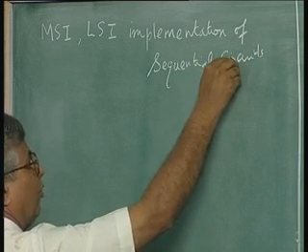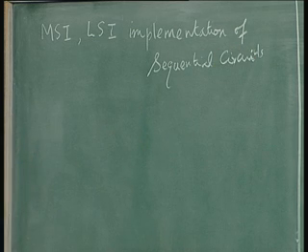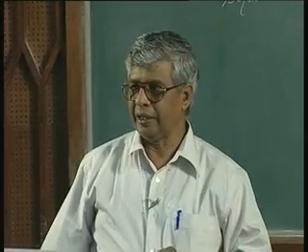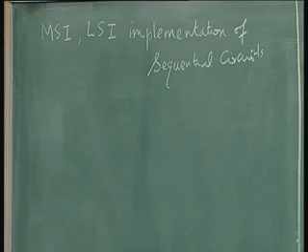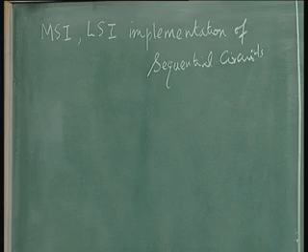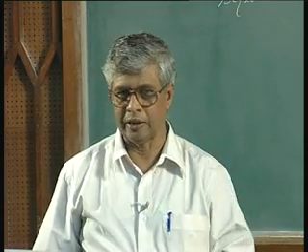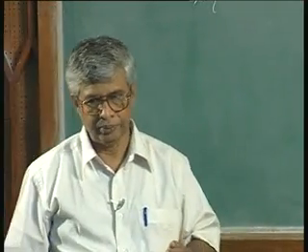I want to emphasize this point once more: when I say sequential circuit, it has a combinational and a sequential component. The combinational part will use all this MSI LSI we discussed. Of course, you will also see that we can do the sequential part too. For example, the programmable array logic we saw had its own flip flops. That is what we discussed last time, and those can be utilized for the sequential part of the circuit, to implement the states. So it is a combination, an integrated effort.